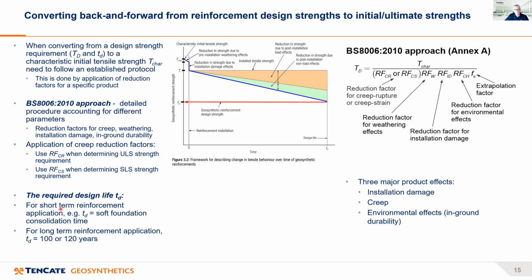The thing to remember, of course, down the bottom left, is for short-term reinforcement application, such as an embankment on soft foundation, the time period, the design life here, may only be relatively short until the soft foundation is consolidated. So it could be 5, 10 years.